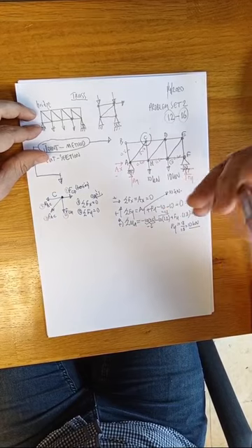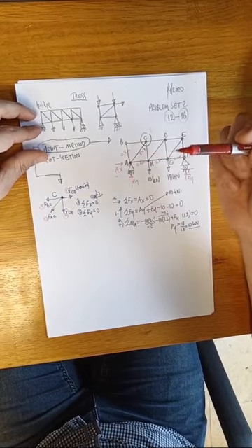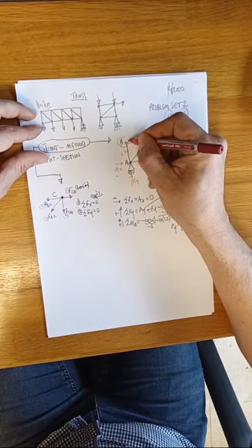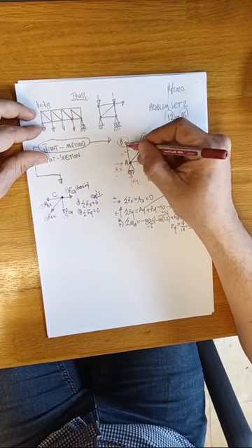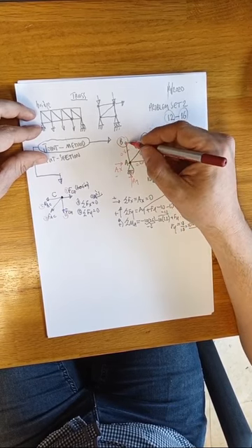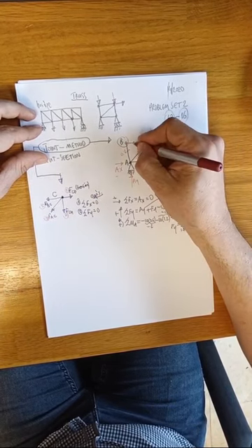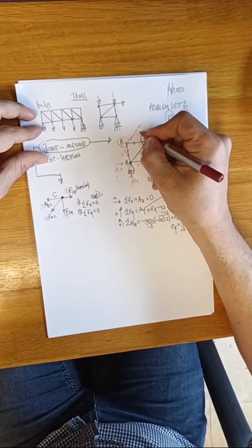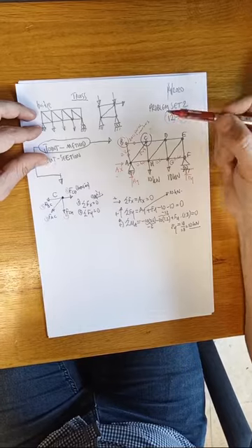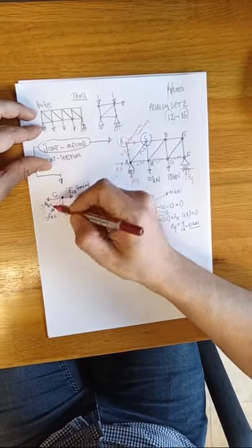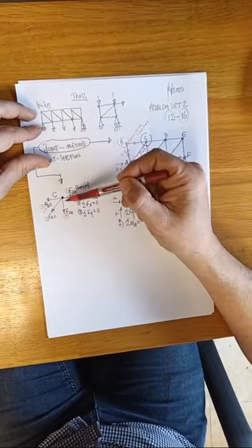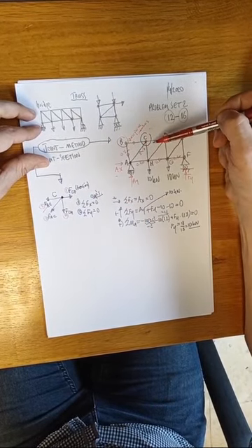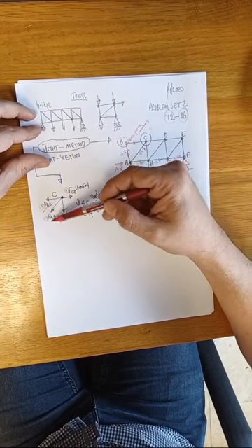Your solution strategy follows, first of all, an easy point here. Where is the easy one? I see there. This is the B point. Because the B point has only 2 arms, as you see, and easily when you draw the B like this, what you will see, these are 0 members, okay? We call them 0 force members. Now I know one of them, FBC is 0, okay? Skip it, but there are still 3 forces here, so you cannot solve still by taking 2 equations, 3 unknowns.